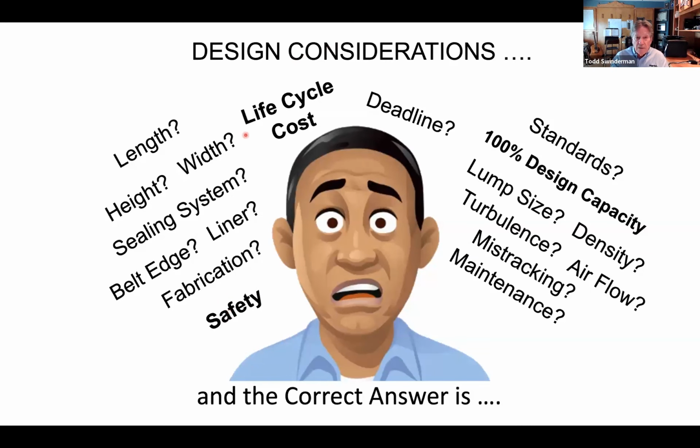Life cycle costs, that's looking at the cost of your conveyor over its lifetime. We may have gone through these calculations, and our cross-sectional area says, well, for this 36-inch belt, it's going to be rubbing on my wear liners for 3 or 4 inches 24/7. So why don't I look at a 42-inch belt?